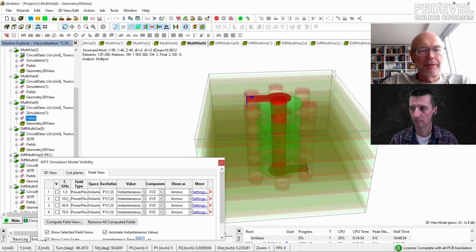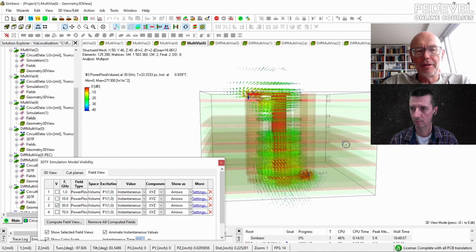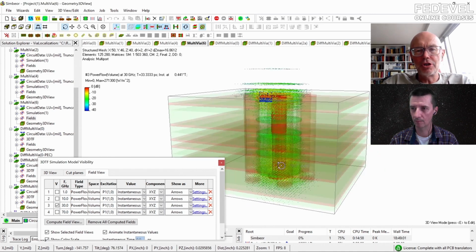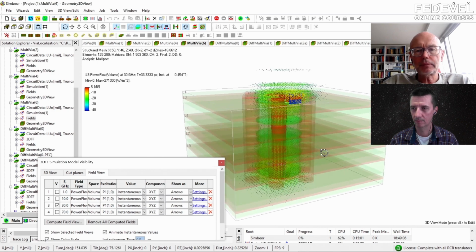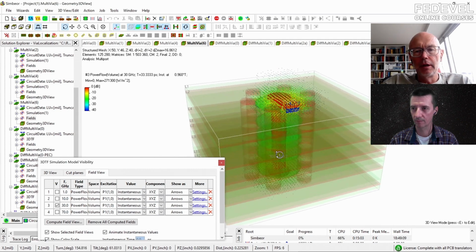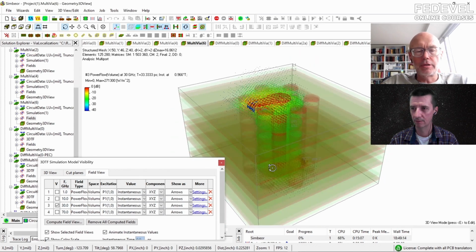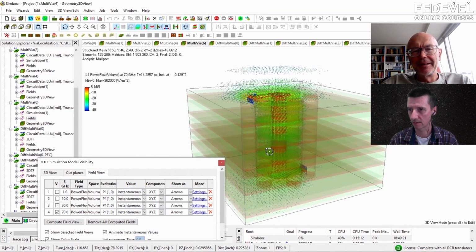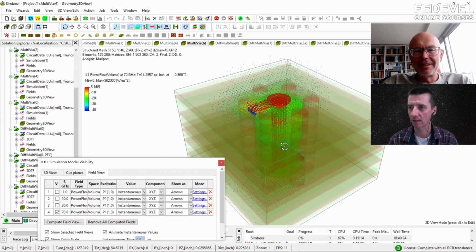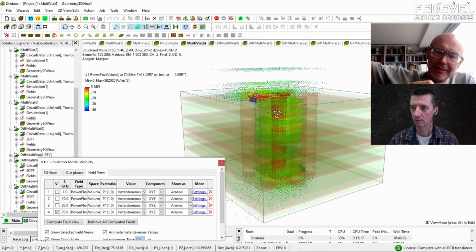To make it absolutely perfect, you make them like this. So 30 gigahertz here, immediately 30. You can see at 30 gigahertz, same scale on the power flow density, and you have all the energy getting so much nicer. Much nicer, yes. And let's just take a look at 70 gigahertz. So this is 6 vias, correct? 6. 1, 2, 3, 4, 6. Yeah, 6, exactly. At 70 gigahertz, it starts radiating up.